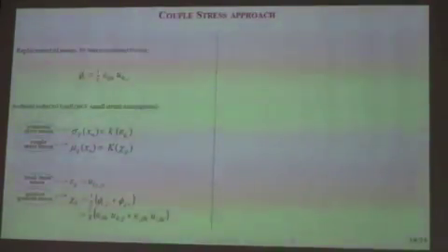So this gives a dependency just on the displacement and the displacement gradients that will follow. So there are suitable reduced forms for the small strain assumption. We can use for the stresses that are now symmetric again. We can show it by energy considerations.